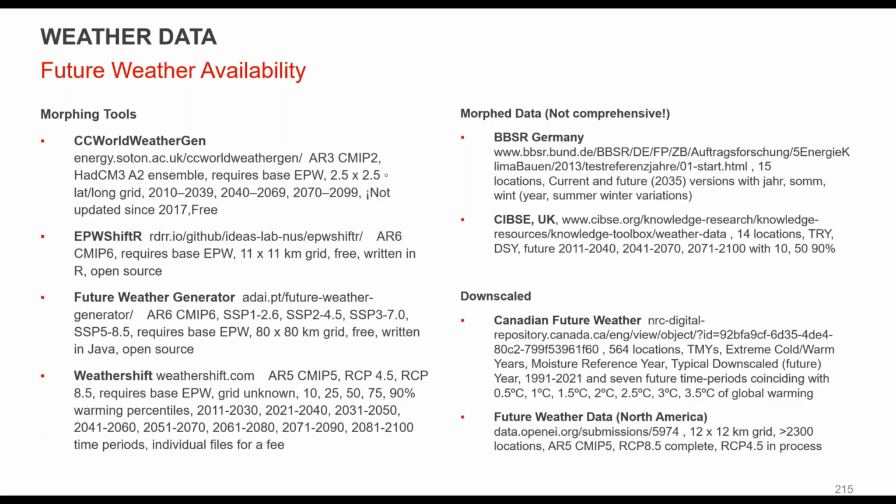Annual percentiles, Jose asking again. A percentile is just a number of hours. If you take 8760 hours and say 1%, 1% of 8760 is about 88 hours. That's what it means on an annual basis.